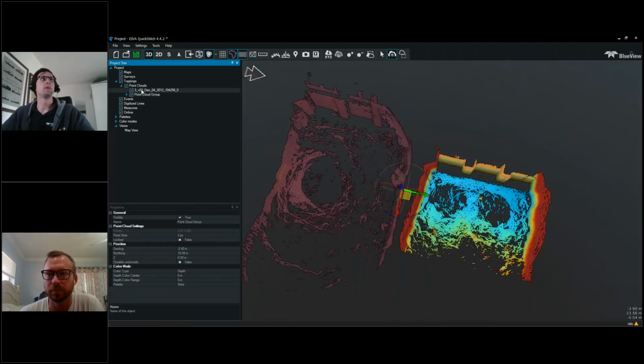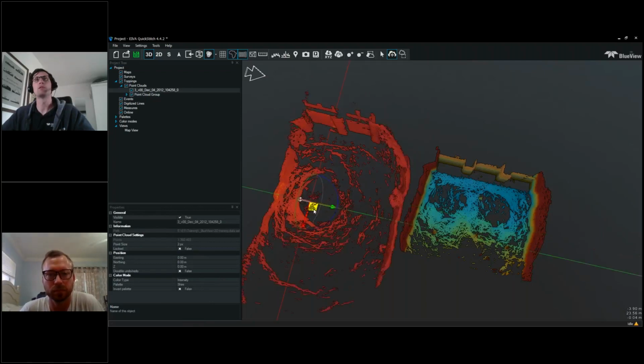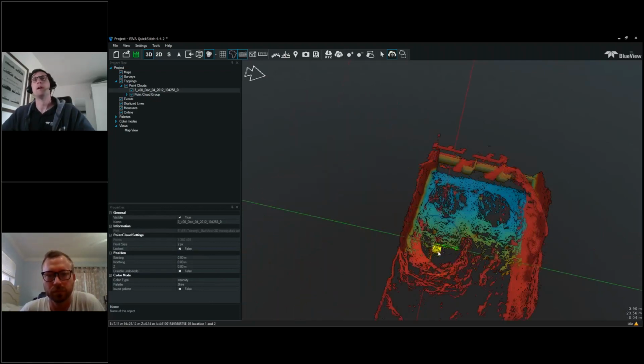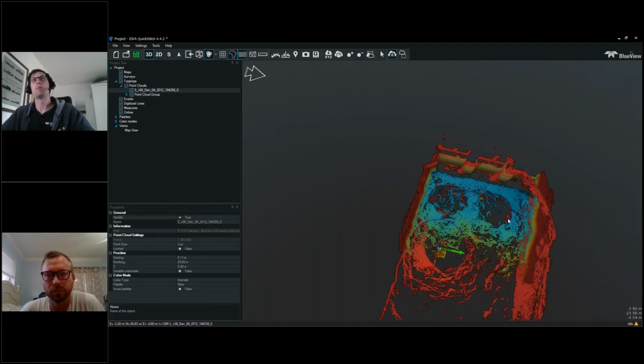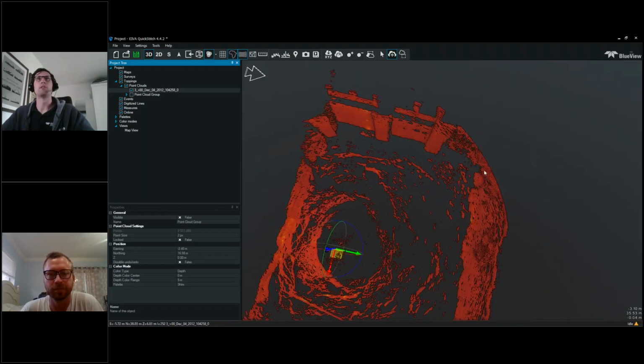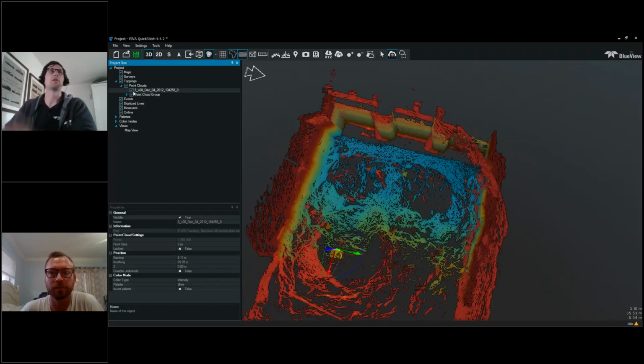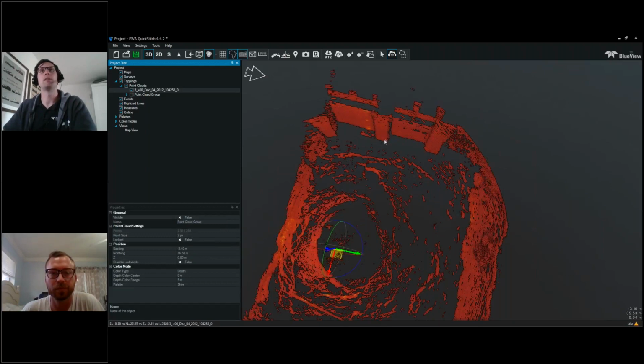So for example, if I were to try to register this point cloud 3, so location 3, which is right here. We can see a lot of the points overlap here, but for location 3, these points further away are not going to be nearly as high a resolution as these locations, which are much closer to this wall, right? So the closer the sonar is to an object, the better resolution you're going to get. So instead of stacking points on top of each other, like we're doing here, for point cloud 3, I know the data on this wall is just not as good.